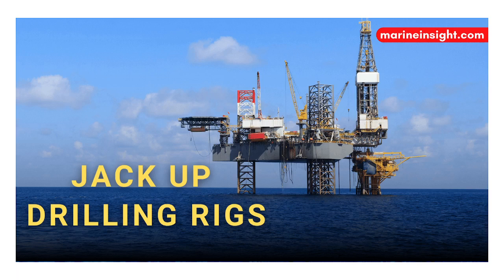Okay. Then there is one platform called the jacket platform. The jack-up platform was the mobile platform, it can move, but the jacket platform is a kind of fixed platform. It will consist of a steel tubular frame, and it will be piled into the seabed. Directly one fixed structure will be there, piled into the seabed.